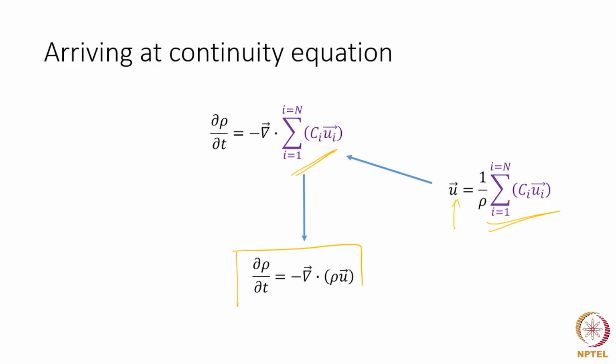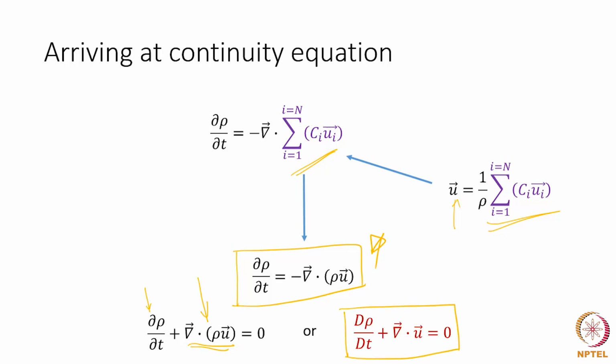Now this is something that we have already come across. This is the continuity equation, and we can take it to the left hand side, and it is a form that we have always derived. When we expand this term alone and combine it with the partial derivative with respect to time and introduce what is called the material derivative, then we have an alternate form of the continuity equation, which is also familiar to us from our previous lessons. And in case the fluid or the material in the domain is an incompressible fluid, then we define that as the continuity equation having the divergence of velocity as 0. So all those things now make sense, because the concept of mass balance is quite embedded in the idea of macroscopic as well as microscopic pictures with respect to the mass balance.